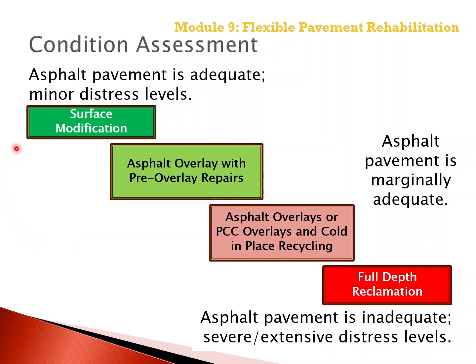Obviously, asphalt pavements that are considered structurally adequate and only have minor distress levels would only need surface modification with or without non-structural overlays. As the asphalt pavement becomes marginally inadequate, then asphalt overlays with or without pre-overlay repairs can be needed.